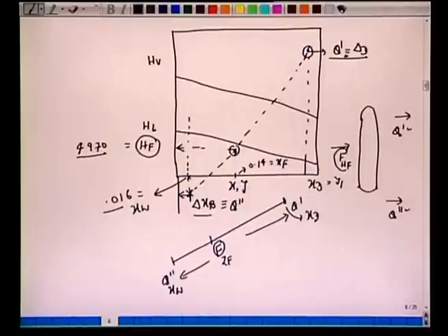All right. Alternatively, again, one can go back and write down this species balance between these three points Q', F, Q'' to numerically calculate Q'. So I leave it to you whether for this point identification of Q' or this Q'', either you make calculations or you make use of this geometry. You can take a scale, and reflux ratio is the same. So this segment is the same as this. That's the definition for L0 by D.